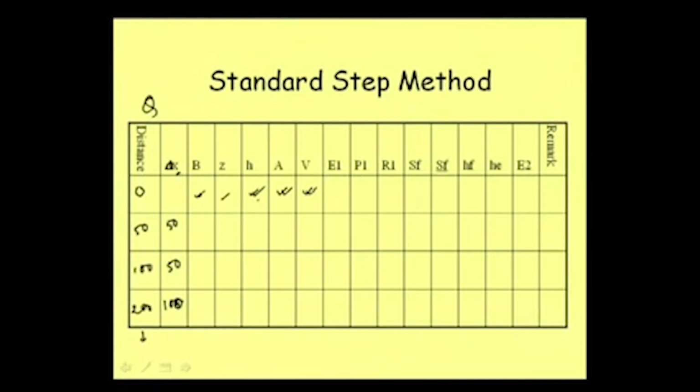So when we know the H and V, then we can calculate the energy at section 1, that is H1 plus V1 square by twice g. Okay, so this is known.